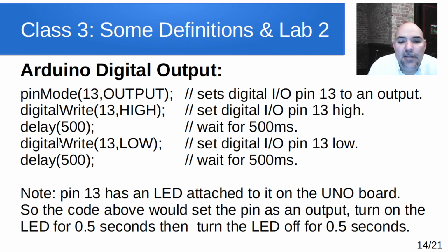So note that pin 13 is attached to that LED on the Uno board. So the code above would set the pin as an output, turn on the LED for half a second, then turn it off for half a second.